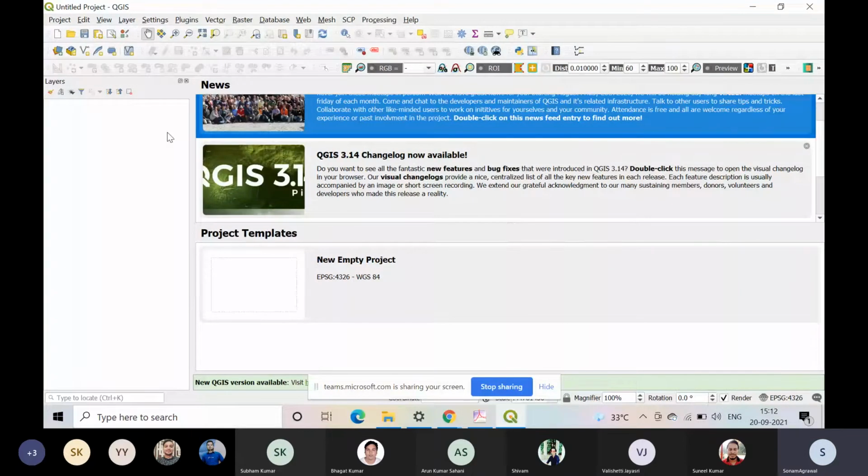Okay, so make sure that you store all the things in a very systematic manner, with a proper naming convention. Okay. Second thing is related to the naming convention. Whenever you create a shapefile or any other file, it is a general suggestion that you must not use any special character except underscore. Okay, except underscore, do not use any comma, hash, ampersand and other things. Name your shapefile properly, so that it represents whatever feature is digitized inside that shapefile.